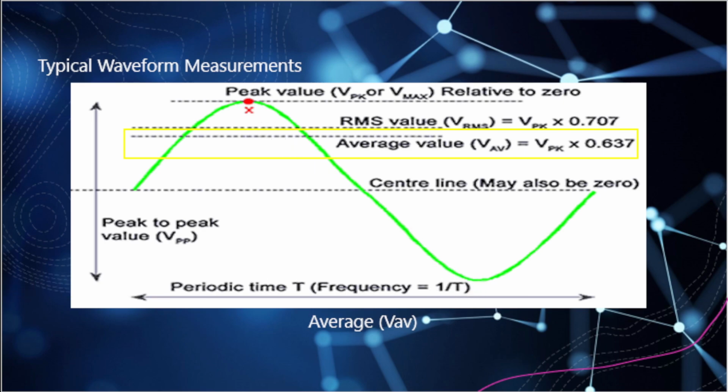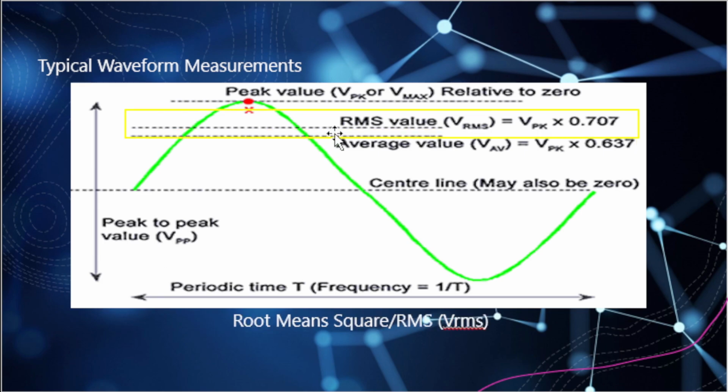Okay, is there another way we can measure it? Of course, RMS voltage. An RMS measurement, root mean squared, typically abbreviated VRMS, is a measurement of your peak voltage times 0.707. That average is slightly higher than your voltage average measurement, and thus displayed on this graph as a dotted line a little bit above.